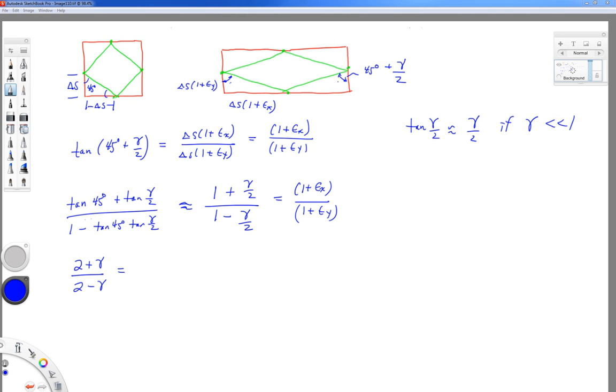All right, so doing a little bit of algebra, now on the right-hand side, on the top, I have 1 plus epsilon x. And on the bottom, because of the Poisson ratio relation and the fact that we have a uniaxial stress state, I'm going to rewrite this as 1 minus nu epsilon x, Poisson's ratio.